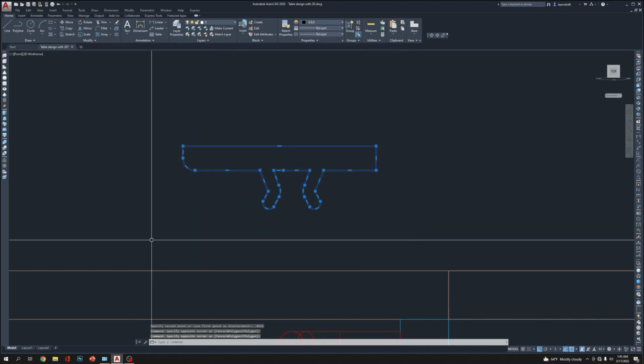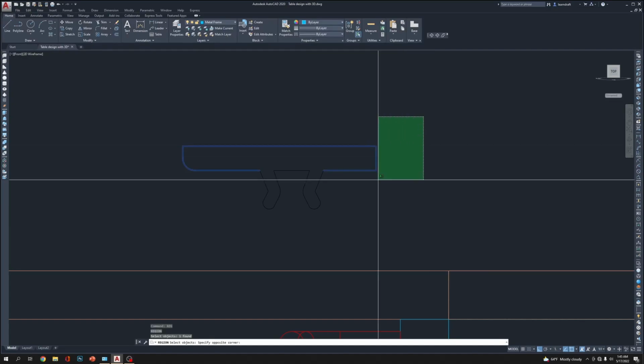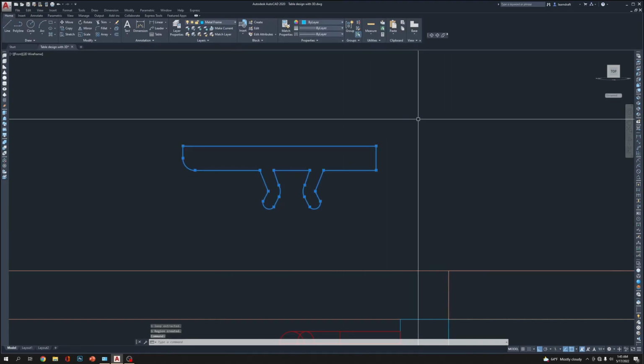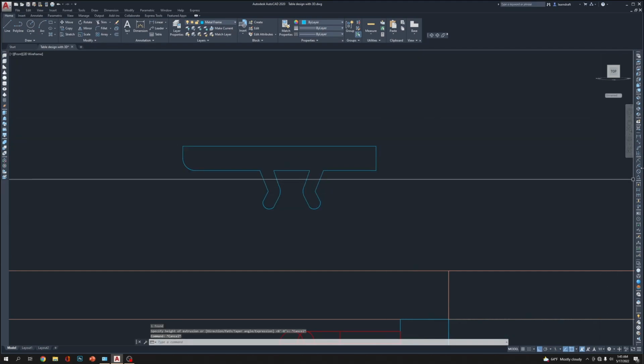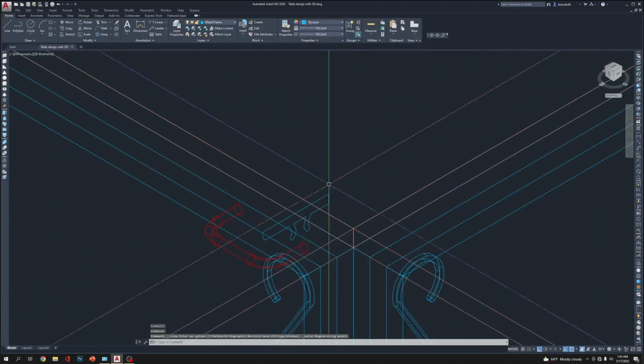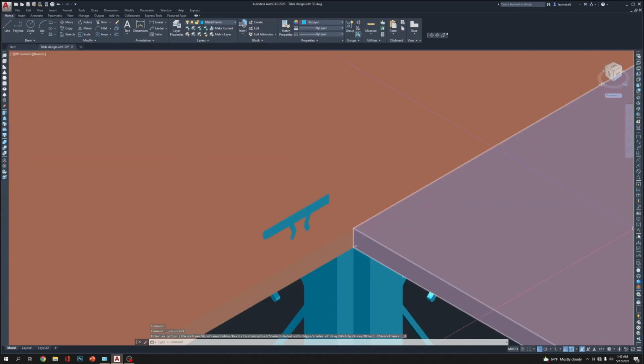Okay, I have selected the region tool. It's gonna make it like, actually like 1, extrude it. No, let's go to the isometric view to extrude. Make it 3D. Make it wireframe.